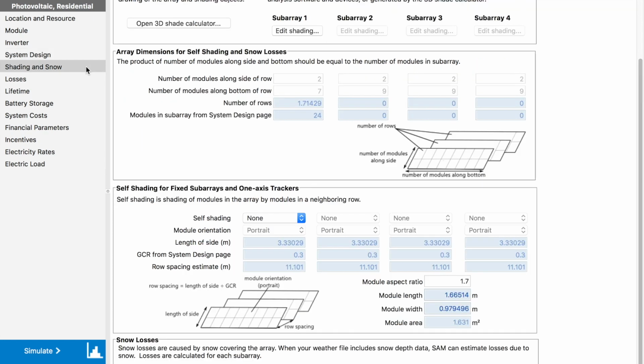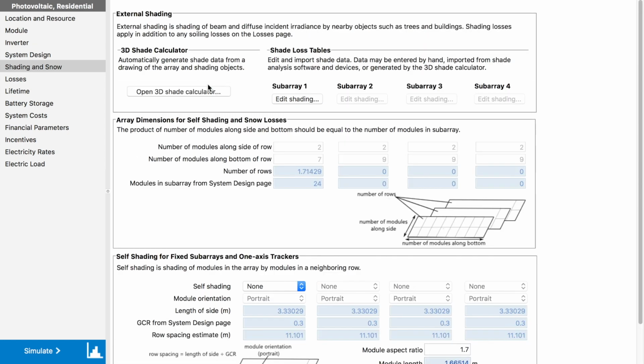The next step is to determine shading. We will assume that this home is set in a treeless lot with neighboring homes not shading the roof or the panels on our home. This is typical for new commercial construction homes, which are typically built in empty lots in pre-constructed neighborhoods where the lots are cleared of trees and the neighboring homes are the same height. Due to this, there will be no outside shading. If there was shading, it could be modeled using the SketchUp program, and the data could be imported to SAM through the use of the Skelion plugin.